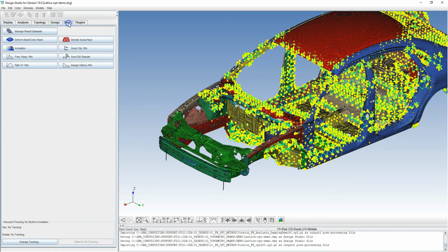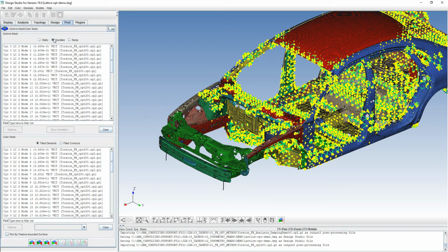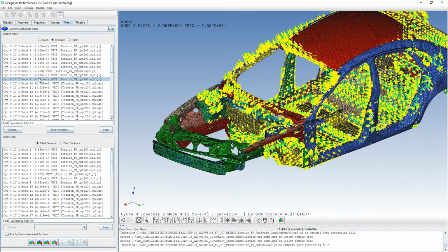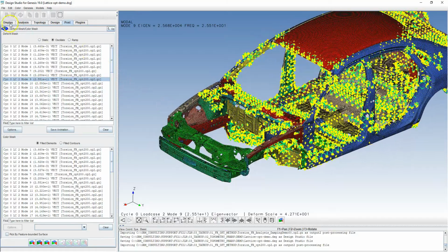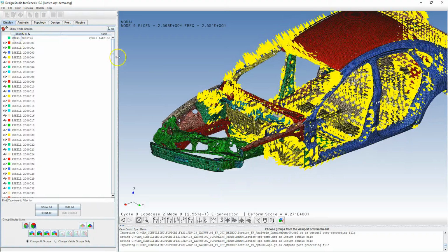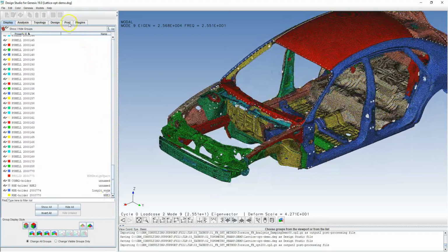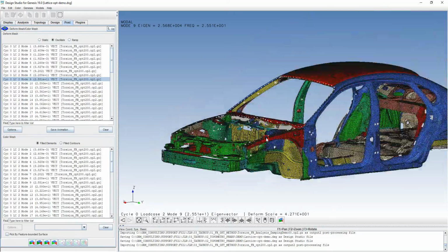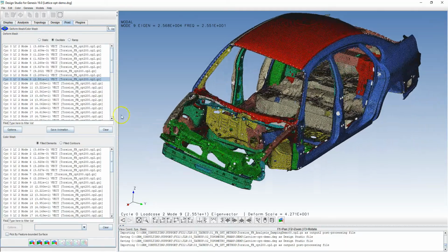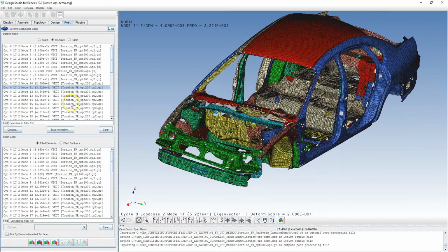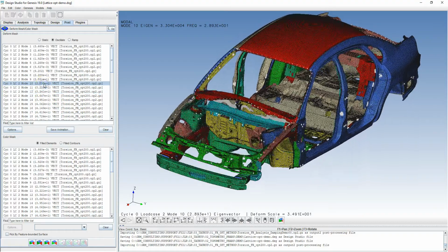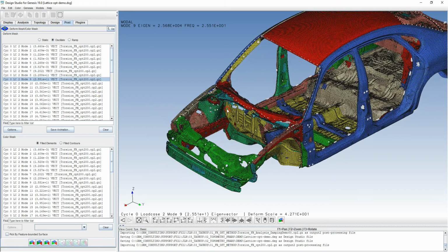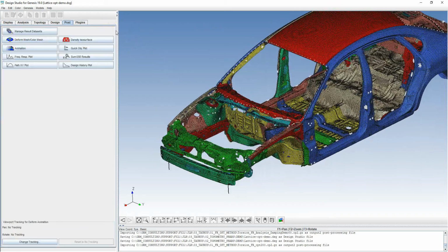If I just take a look at the results in the model, you can see here are the modes. I know this, having looked through already, is the first mode. I should just add this is with the lattices not in place. This is the mode that we want to identify, but it could easily be confused with the second mode or third, and so you start to see some unclear natures. So we're going to optimize for this first mode, but we're going to use the frequency response approach for that.